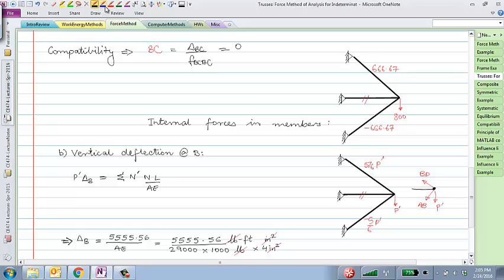The equation would say basically that 2 BD times the sine of that angle, which is 3/5, has to be equal to P prime. So clearly 2 times 3 is 6, 5 goes the other way, so we get 5/6 P prime. Okay. Yeah, 5/8 was actually when we cut this member, so that's a different loading scenario. So yeah, back to this problem now.